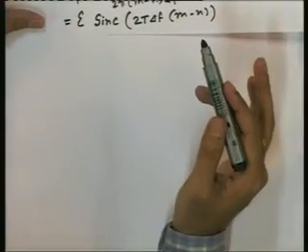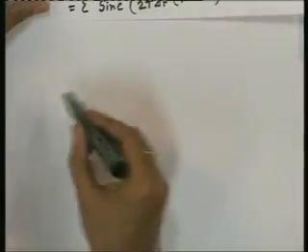That is a very special question, because we will see that for an orthogonal signal set we can do the demodulation very easily. So we will see now for what values of delta f this will be 0 for all possible m and n. For any m and n, this will be 0. That is true for what delta f, that we want to see.